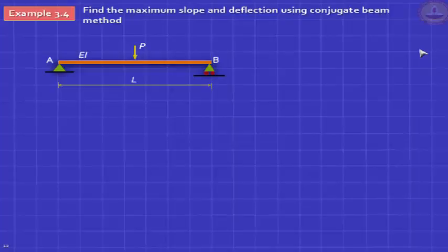So now let us see what happens if you had a concentrated load in the prismatic beam. And we don't want to derive the expression. Practicing engineers don't want to waste their time. Just we want to know the maximum deflection and the slope. Maximum deflection, remember the formula, PL cubed by 48 EI. We are now here to prove it.